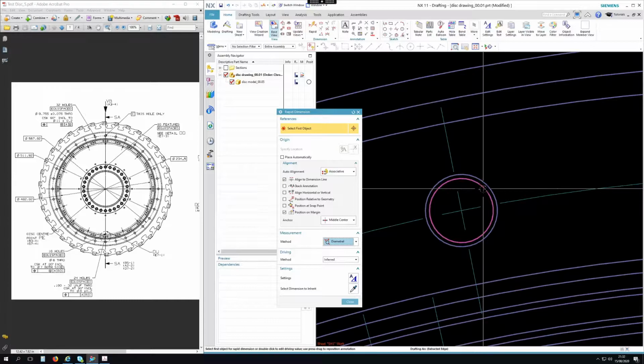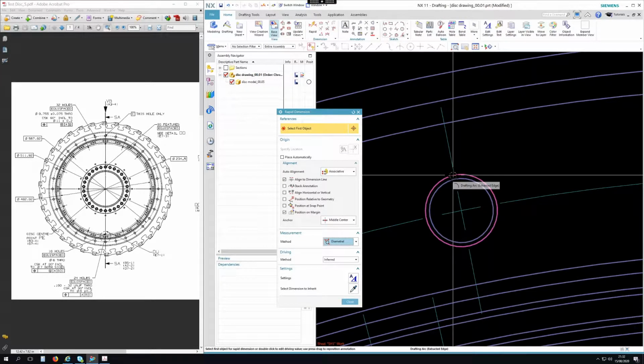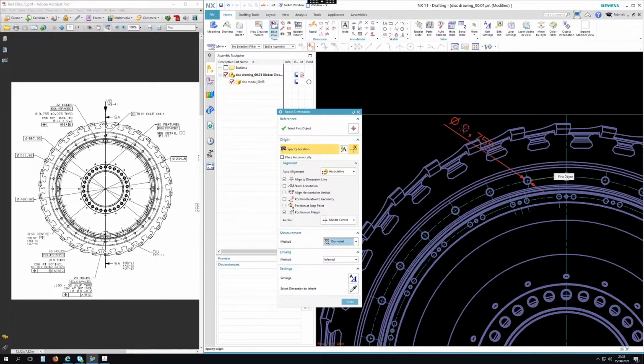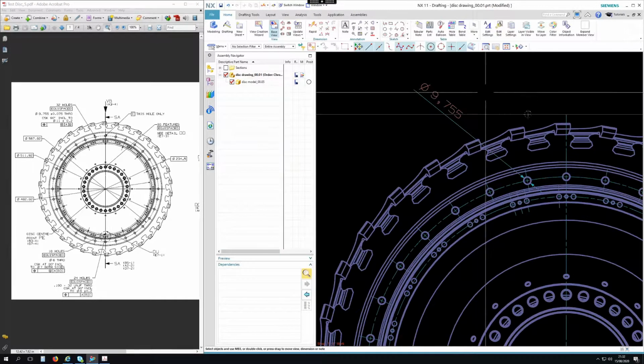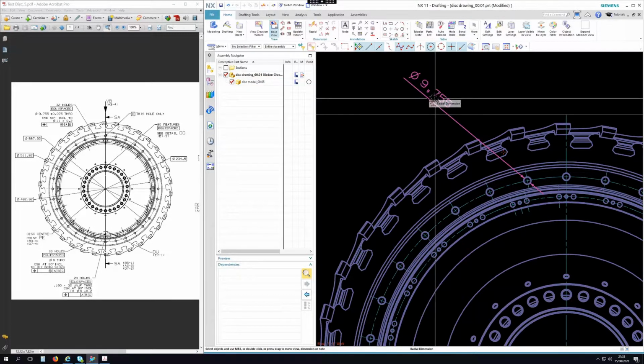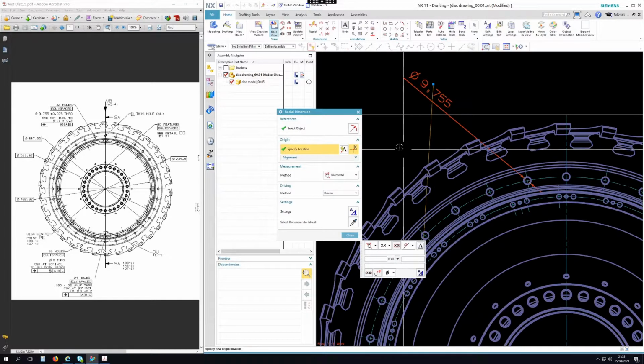And it's the inner one we want to pick, because the outer one is the countersink. So pick the outer one, place that down for now. Right, so we've got the diameter, that's parametric. If that hole size changes, this will change with it. So let's double click this.